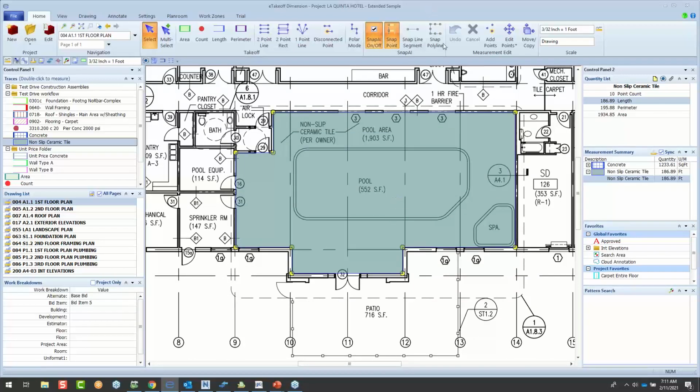So let's take it a little bit further. Maybe I need to remove this area right here from this takeoff. Well, I hit my G key, snap, done. So you'll notice there's curves right here, and this automatically adhered to that line going through the process. So in this process, we're going to give you that efficiency.